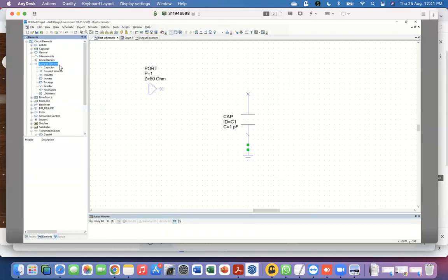Lumped element basically means, and the term opposite to this is called a distributed element. So something which is extended in space, distributed in space, versus something which is like a point object. Even though we have seen capacitors and inductors and they're not point objects, the reason they are called that is that it depends on their size relative to the wavelength of electromagnetic radiation at the frequency you are operating on. So in that context, they are almost point-like. And if that is true, they're called lumped elements.